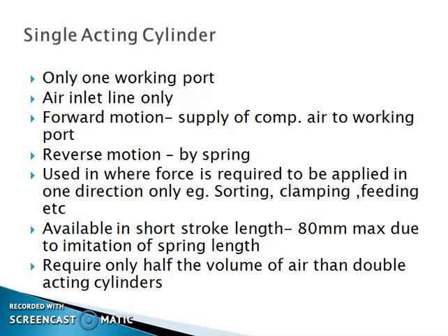Next topic is the single acting cylinder. A single acting cylinder has a single air inlet. It has only one working part. During forward motion the piston is moved by the compressed air supply, and the return motion of the piston is by the spring placed on the rod side of the cylinder.